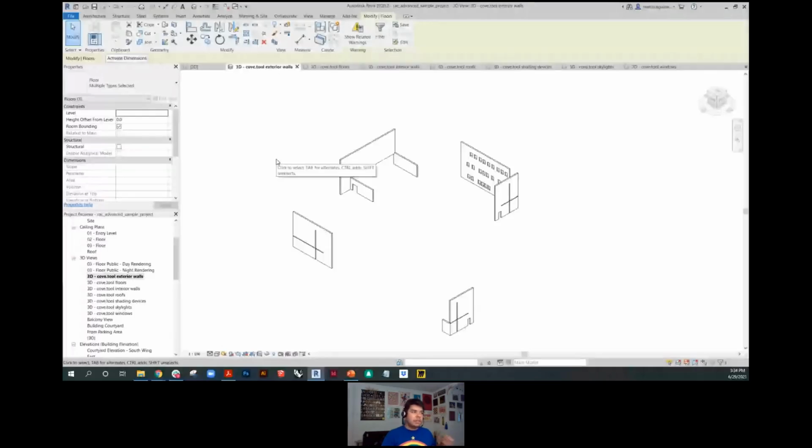In the new Revit plugin version, since we're adding the spandrels layer as one of the new categories you can export, we do now have a way to separate opaque area versus glazing area or translucent area. So that's going to be a lot easier, especially when working with curtain walls.